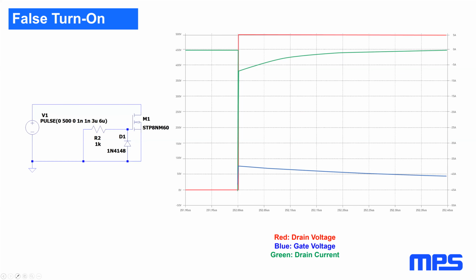When the low side MOSFET turns off, the voltage at the drain rises quickly due to the current flow through the inductance. That can cause the low side MOSFET to turn back on. Also, the high side turning on and driving the output high can cause the same thing, and that can cause shoot-through. Since the high side MOSFET's turning on, the low side MOSFET will turn on and current will flow directly from supply to ground.